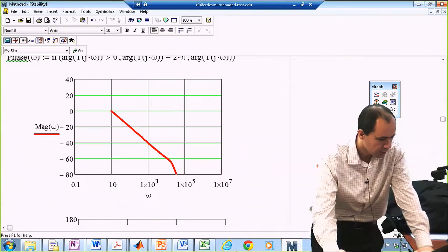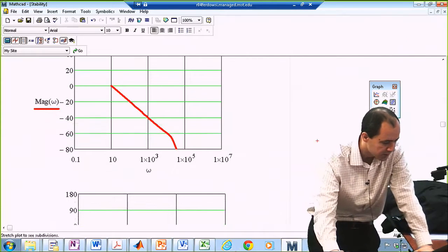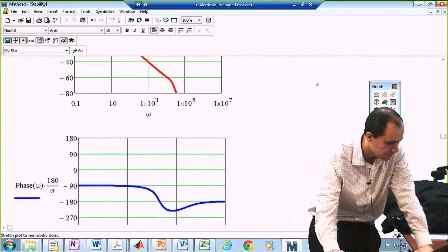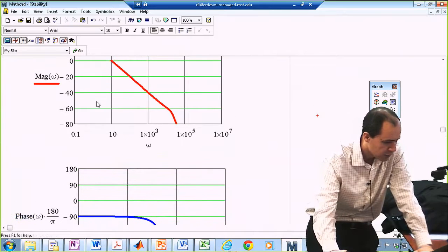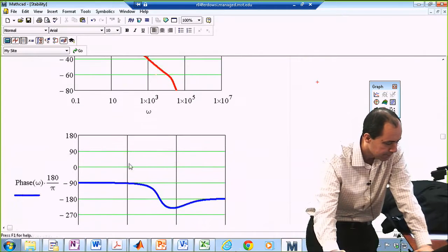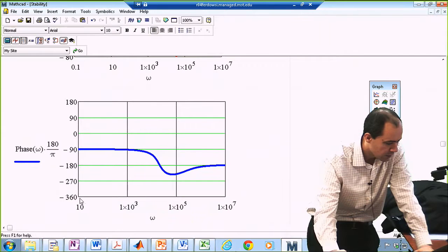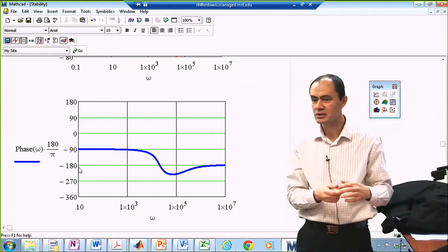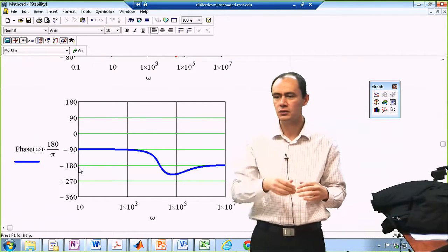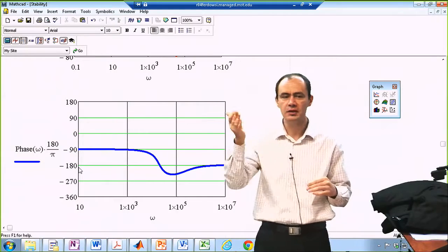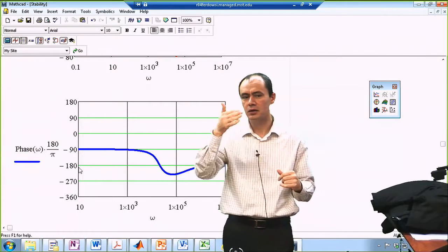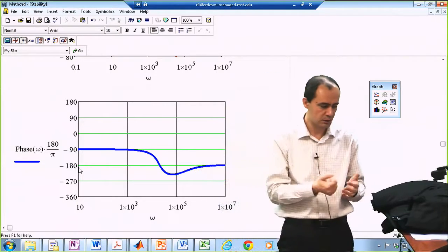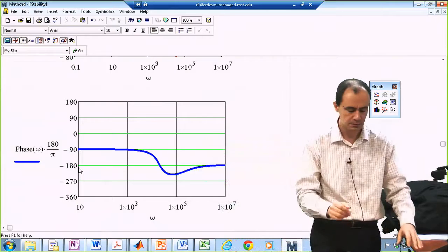All right, what about the phase margin in terms of stability? Okay, so my crossover is 10. Let's evaluate my phase margin at 10. It is actually about 90 degrees. It's a very stable system. As you can see, we did not even see any overshoot. It was just like a first order behavior. It was going from 0 to 1. It did not even peak at all. This is like an overdamped kind of a system.